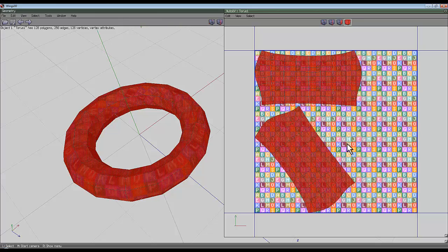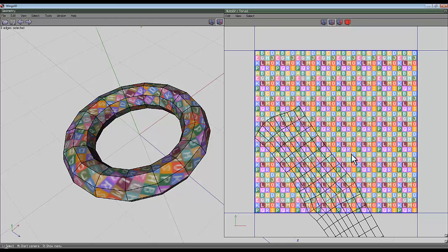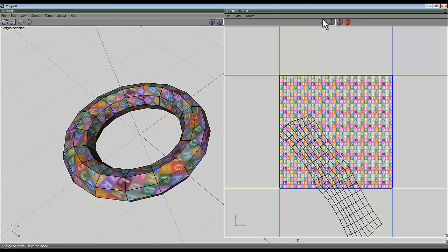We end up with these two segments. So what I'm going to do is stitch those together along that edge there. So just select stitch. It's come off at a bit of a funny angle, but I can straighten that out. So actually those edges are selected there. If I get that edge and make that orientated with the y-axis, which I do using my rotation option here.